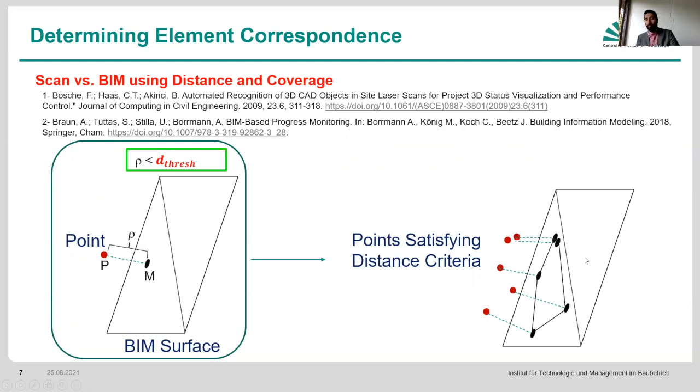And this is basically where we're at, meaning that we've performed the ICP and we have a good registration. Now we want to go back and see, now that we know all of these points that satisfy these constraints, and we have these projections, what would be considered a recognized surface here? They take the polygon of the projected points, which is easier because we're comparing it with the original.